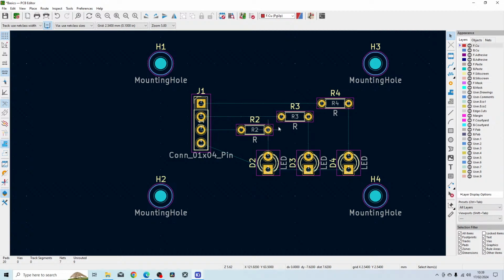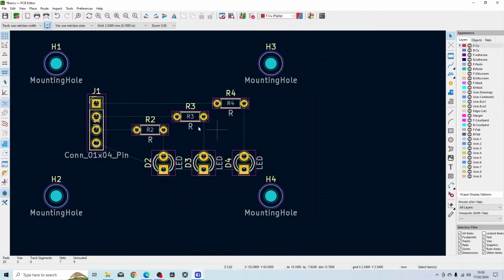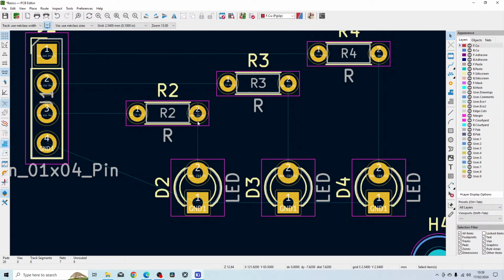Right, so let's now place the tracks. What I've done here is make the rat nest, which is basically showing you the connections that you need to make with the copper tracks. Those are shown with this faint light blue line over here. You can turn that on and off using this function here, because when you have a very complicated design, it can look very messy, so you can turn it off, or you can make it so that it only shows you some rat nest, or it shows you curved lines as well, which can sometimes make it easier to see.